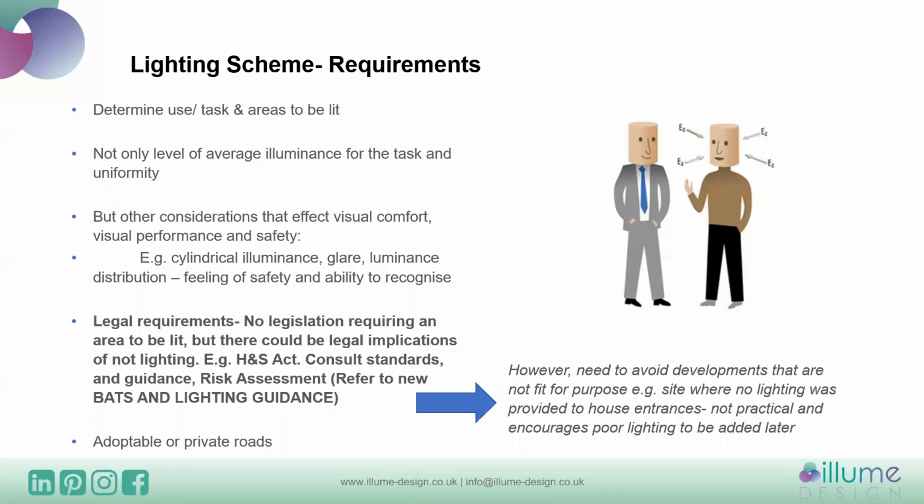Something that's highlighted in the new guidance is about legal requirements. So there's no legislation requiring an area to be lit, but there are legal implications, or there could be legal implications of not lighting an area. So this needs to be carefully considered with the client and the architect to make sure that a risk assessment is in place for areas that are going to be lit to lower levels to make sure that they're still going to be safe and suitable for use. And this is something, as I said, that you can read about more in the guidance.